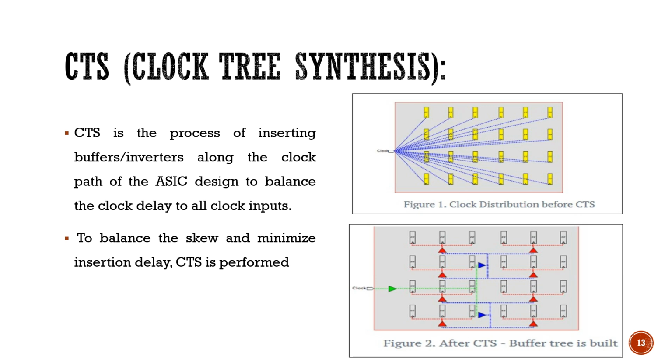Each and every flip-flop will be experiencing a variation in time. The flip-flops that are placed nearer to the clock will be switched on at one particular interval, whereas the flip-flops that are placed away from the clock signal will be experiencing a further delay, right?